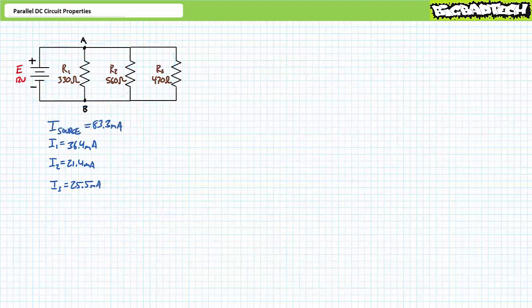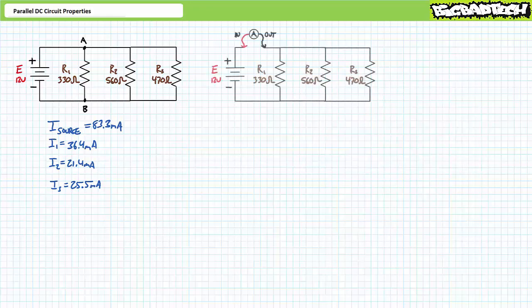Perhaps the most difficult aspect of parallel circuits for first-timers is incorporating ammeters into real-world parallel circuits to measure specific branch currents and source current. You'll no doubt recall that an ammeter must be placed in series or in line with the element under inspection. Ammeters necessitate the modification of the original circuit to do so. Consider an ammeter inserted in this system intended to measure source current.